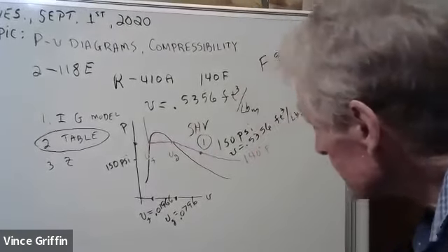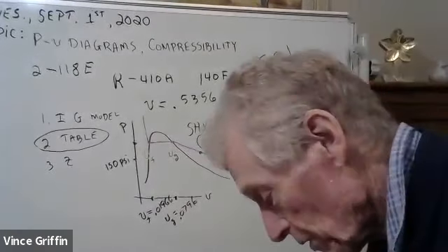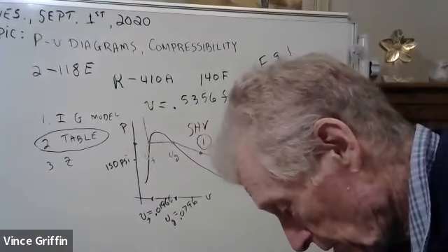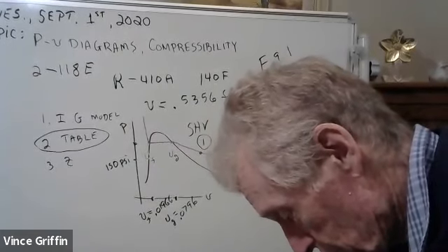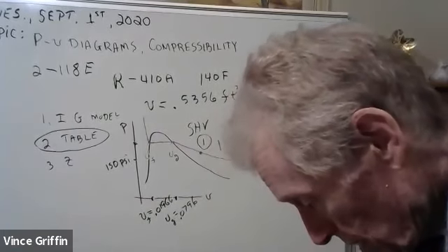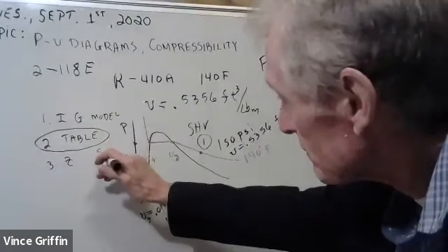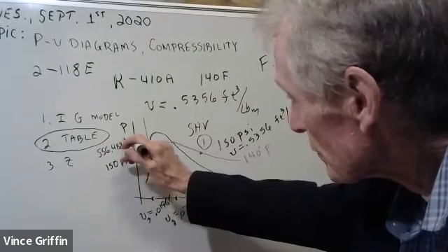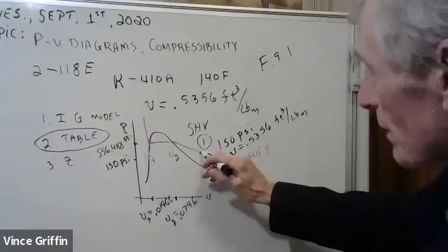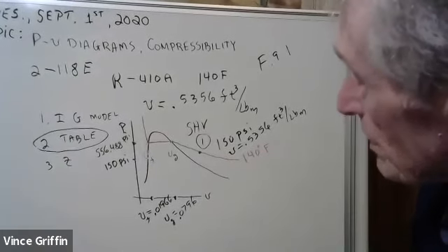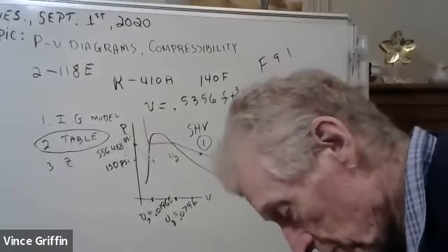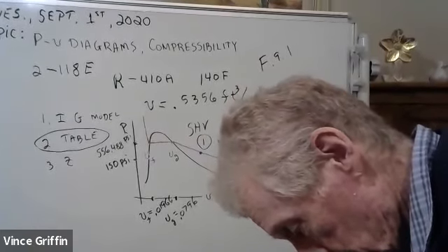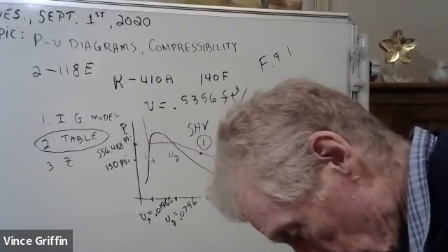See this pressure right here at 140. I don't think I ever wrote it down. But at 140, there's two tables there, and we learned that, didn't we? At 140, the pressure is 556.488 PSI. We are right here, and we've got our pressure. I think that's what they wanted. They wanted the pressure. We found it for them.